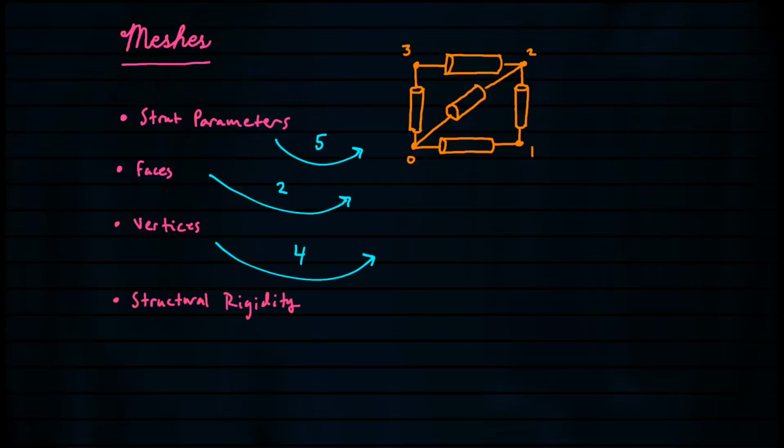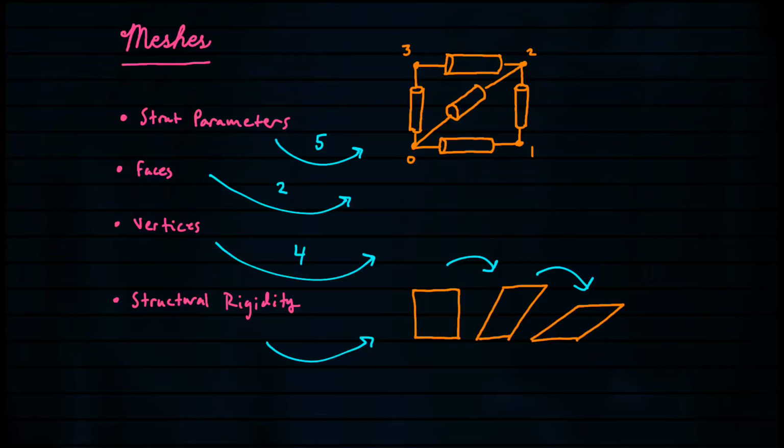So there's an element that we think about which is structural rigidity, and what I mean by this is that if we have a box that has springs, there's nothing that's keeping this box together, and so what could end up happening is it could end up just kind of going over flat because there's nothing holding it up. So a lot of times we might have to add extra struts where we kind of add extra springs holding the box together to add some rigidness to it. There are other methods, such as using a better primitive, like a tetrahedron, all right?